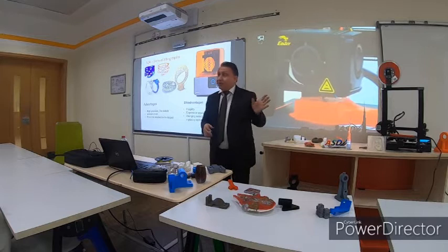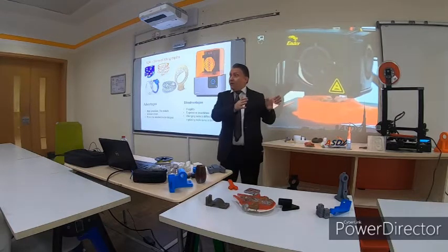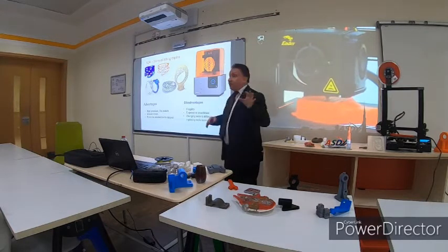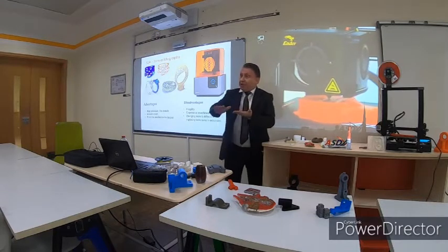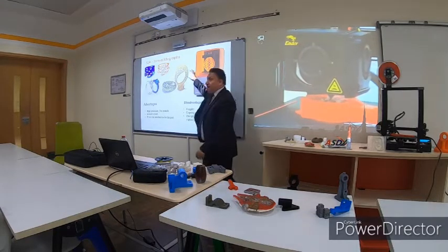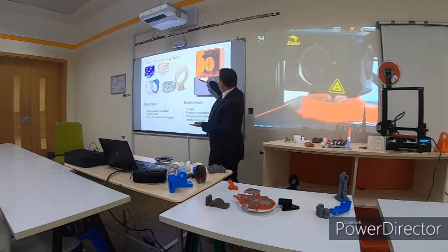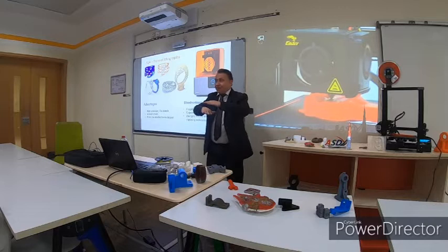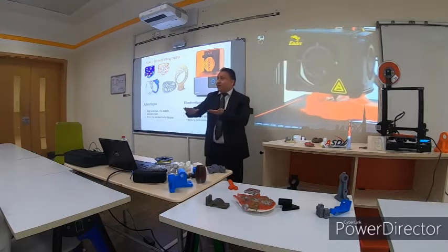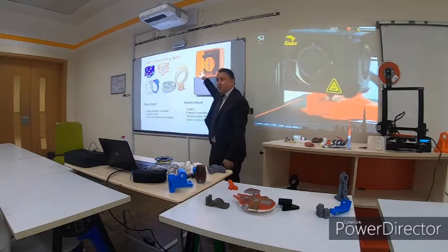This technology is called FDM, fused deposition modeling. It melts a roll of plastic and builds the object layer by layer. That technology uses resin and a laser, and everything is immersed inside the liquid resin. Step by step, using ultraviolet laser, it doesn't require support here.